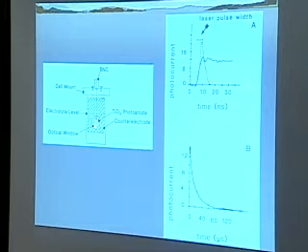There's lots of opportunities at a semiconductor electrolyte interface to generate noise. And so we made everything coaxial. We have a coaxial wire going in through a BNC connector, and we have a counter electrode here, which is a platinum gauze in a cylinder. We cut a little hole in that gauze, and we put our TiO2 electrode right down the center. So the whole electrochemical cell is a coax cell, and that really cuts down on the noise. We carry the coax all the way into the cell, and when we did that, we could get a pretty reasonable signal.